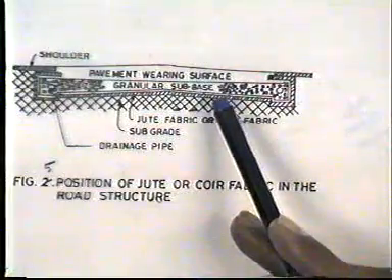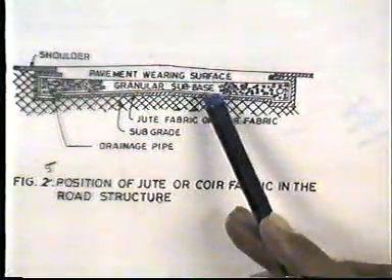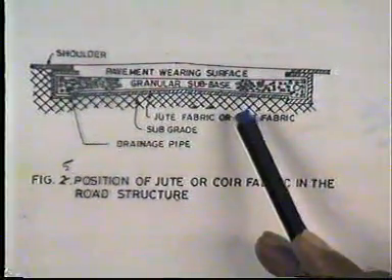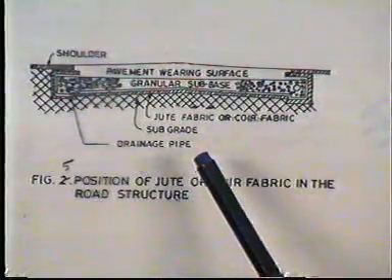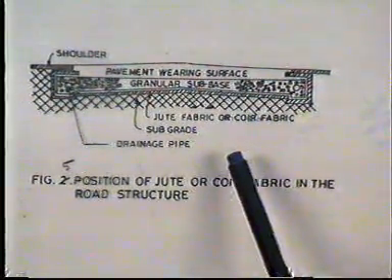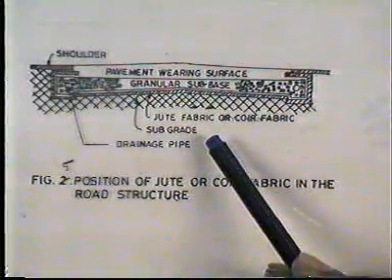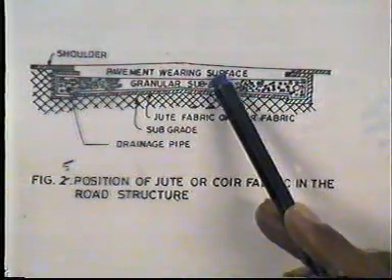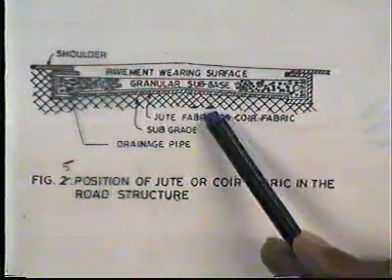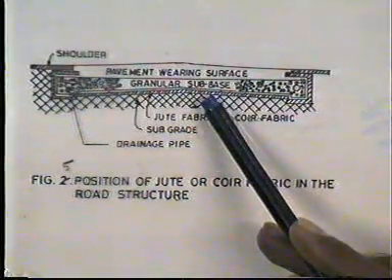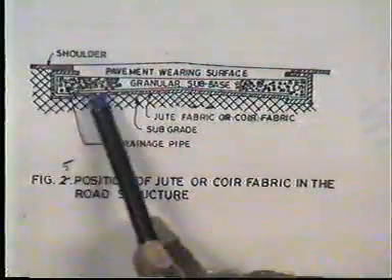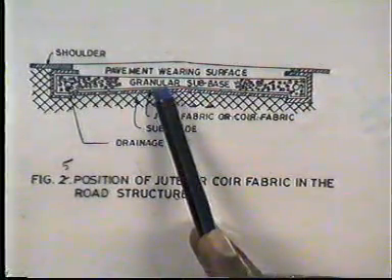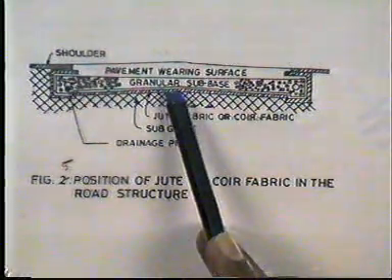It acts as a membrane and separator to spread the load over a wider area, as well as prevent subbase material punching into the softer subgrade.